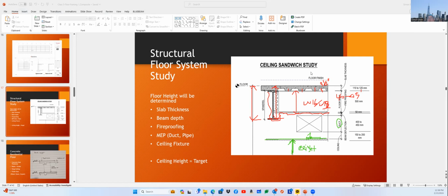So the reason why this is very important is if you save somehow 1 inch multiplied by your number of floors, 40, so 40 inches saving. It's not only structural material saving, obviously all curtain wall and all plumbing, everything is really adding up. And since in a high-rise building we're dealing with multiple floors, the floor framing system study is very crucial. So I want you to be aware of this.